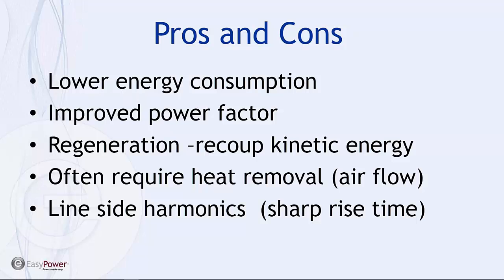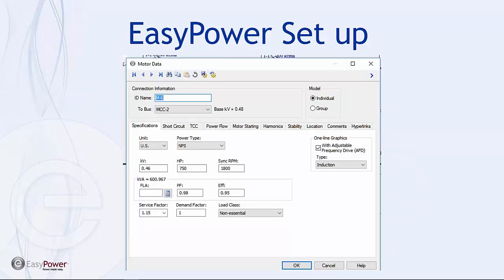And then, as we could see from the waveform, there is going to be a fairly high concentration of harmonic generation because of the rise times involved, and some thought needs to be given to the effect of those harmonics on our system, whether in terms of filtering within the VFD itself or filtering in the system, based upon the way that they're getting out of the controller. So with all that in mind, let's jump into EasyPower and see where this is going to take us.